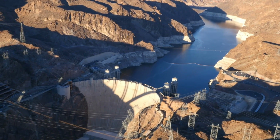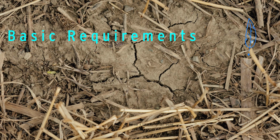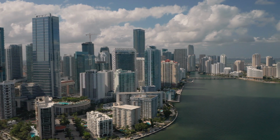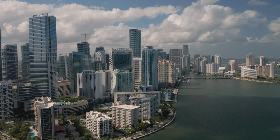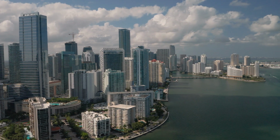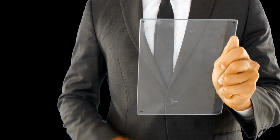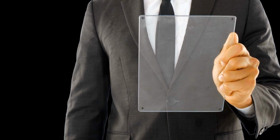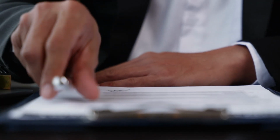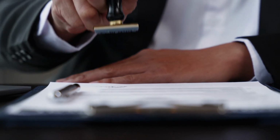Today, we will discuss how to estimate water demand for a proposed development. Basic requirements. For any proposed development, proponents are required to furnish the city with anticipated figures for average daily, maximum daily, and peak hour water demand. It is imperative that all underlying assumptions be clearly articulated and comprehensively documented. Additionally, the water demand calculations must bear the stamp and signature of a licensed professional engineer authorized to practice.